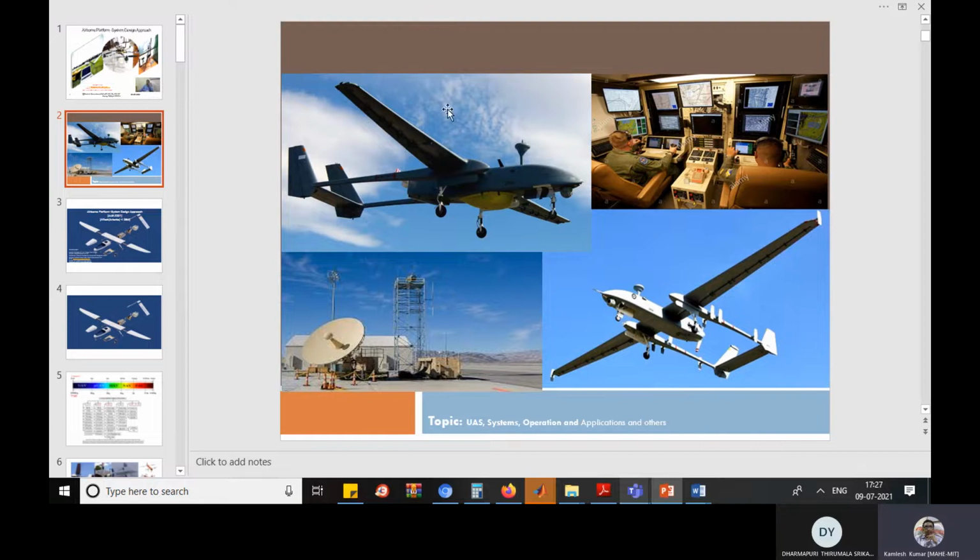So you should have one system with the payloads. What type of payloads is it? Synthetic aperture radars or a basic camera, but you should have one platform to learn under avionics system engineering, because the whole avionics system depends on your platform. Is it your normal UAV, or maybe a bigger UAV like actual drones, or military aircraft, spacecraft, or maybe satellites? You need one type of platform, and only then can you talk about the avionics systems.